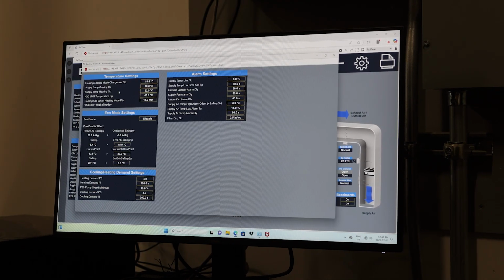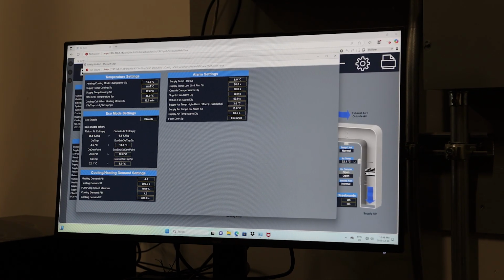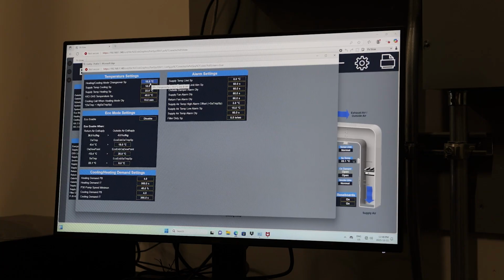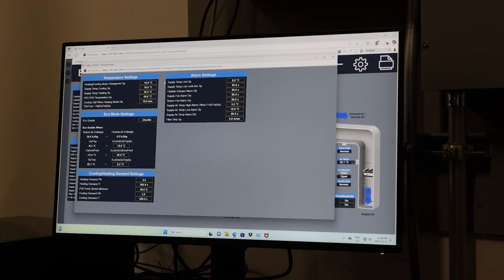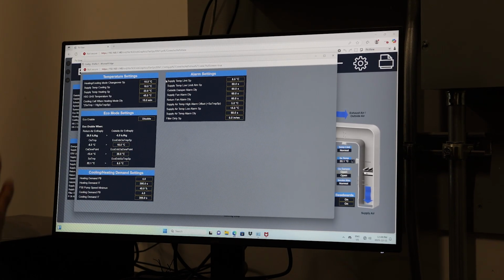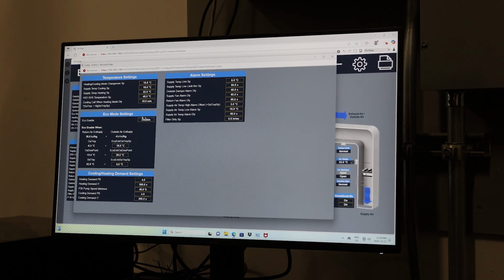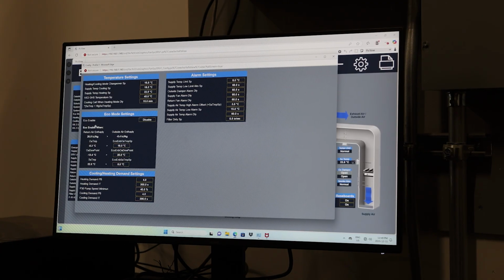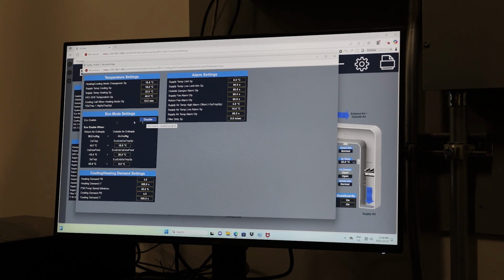And then here, heating cooling mode switchover set point. That is the set point for the ERV to switch between heating mode and cooling mode. It is also based on the building mode, right? Because the building can also be in heating mode or in the cooling mode. Then we will have economizer mode. As of now, economizer mode is disabled.